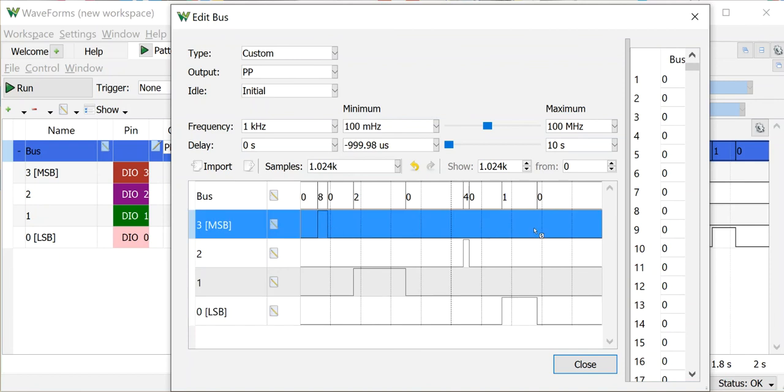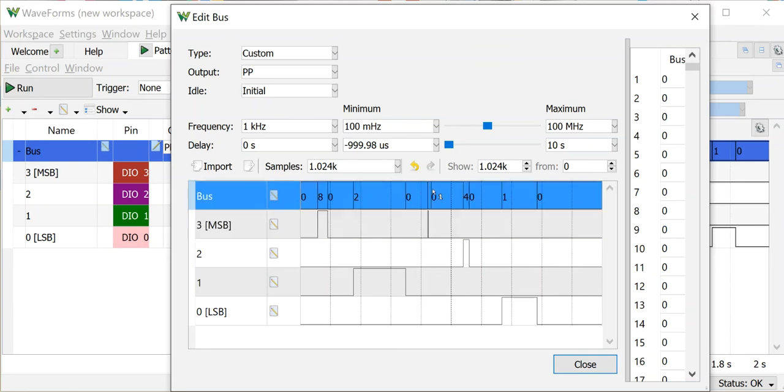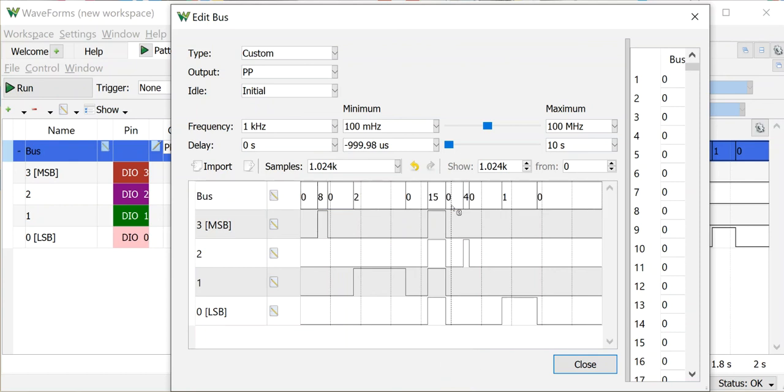One thing that you might want to do is have all 4 of the signals line up a 1 at the same time, and that's hard to do. And they did put something in the software for that. So if I take my cursor, go to the very top, and go on the 1 signal, you'll notice when I drag this over, it does a 1 all at the same time, and the edges line up exactly, and that's what's hard to do manually with eyeballing it.